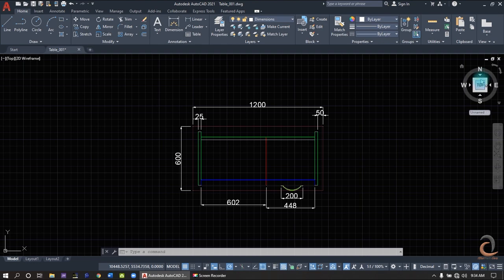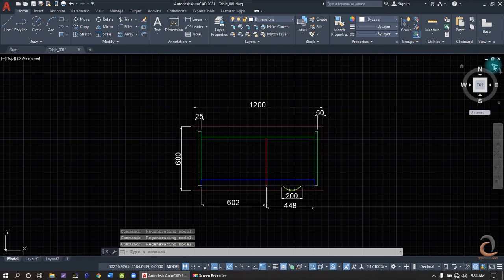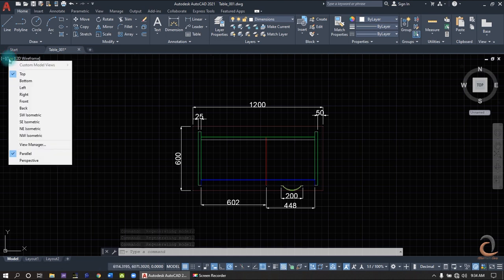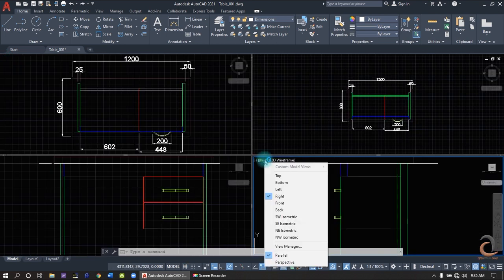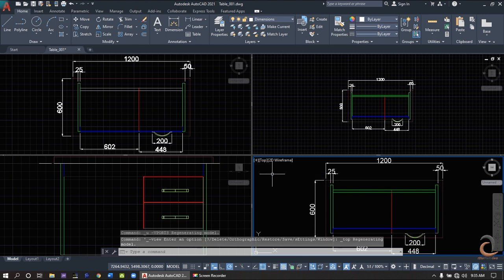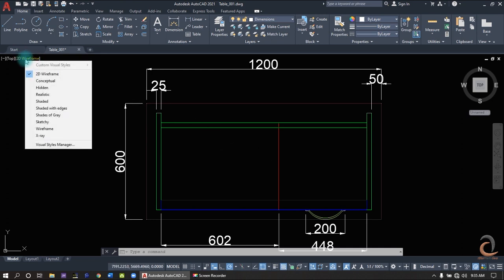You can also rotate your view by clicking the Rotate arrow, and it will rotate your view in 90 degree increments or decrements. To see all available view options at once, go to the top left corner of your model space and click on the top button to choose any view control. Click on the negative sign button to get your viewport controls. Here you can restore your viewport. For maximization, click on the addition sign and choose Maximize Viewport.